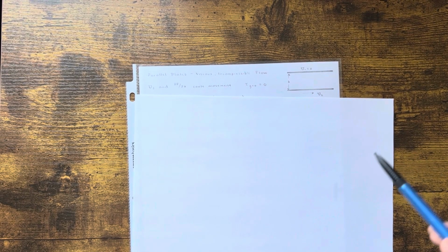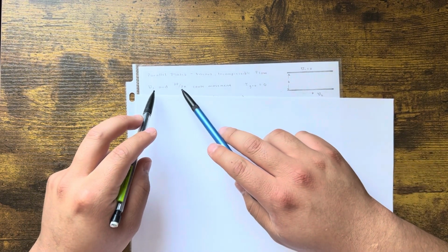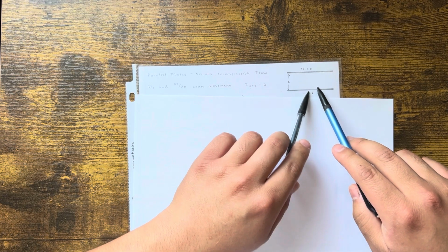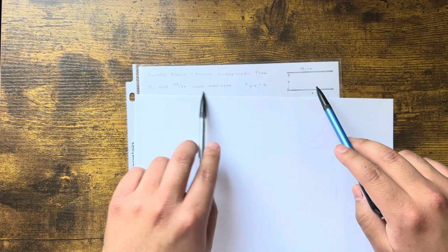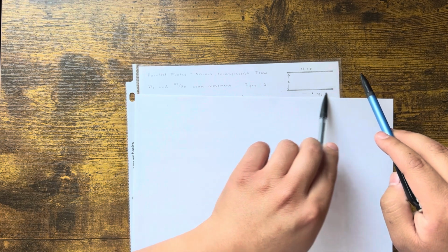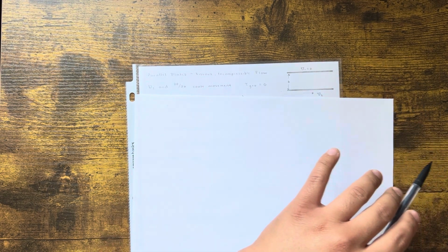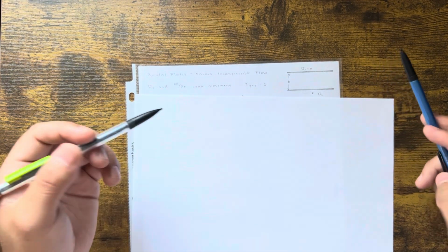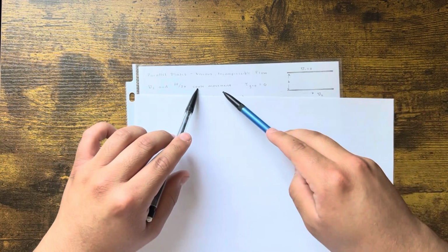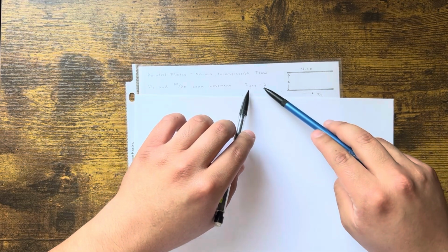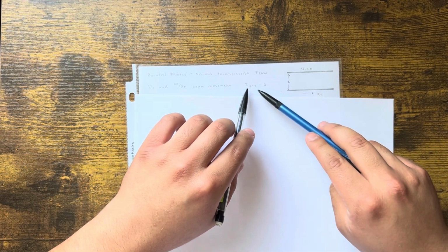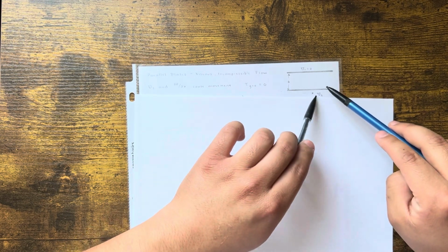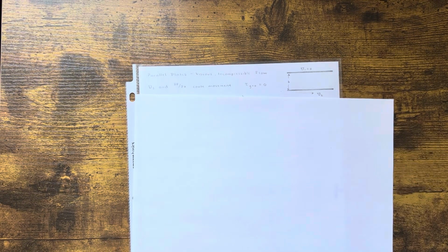All right, guys, so this one's easy. Again, the problem is saying that these two are causing the movement inside. I mean, there's fluid between the two plates, right? And that's what's causing the movement. There's U2, so the plate is moving, so that naturally makes the fluid want to move. And then there's a pressure, so there's probably some pump that's pumping it in the X direction. It's a change in pressure, so that's what's causing the movement. So we know, because of the problem, that we're going to have to set shear stress equal to 0 at y equals 0, right? At the moving plate boundary.